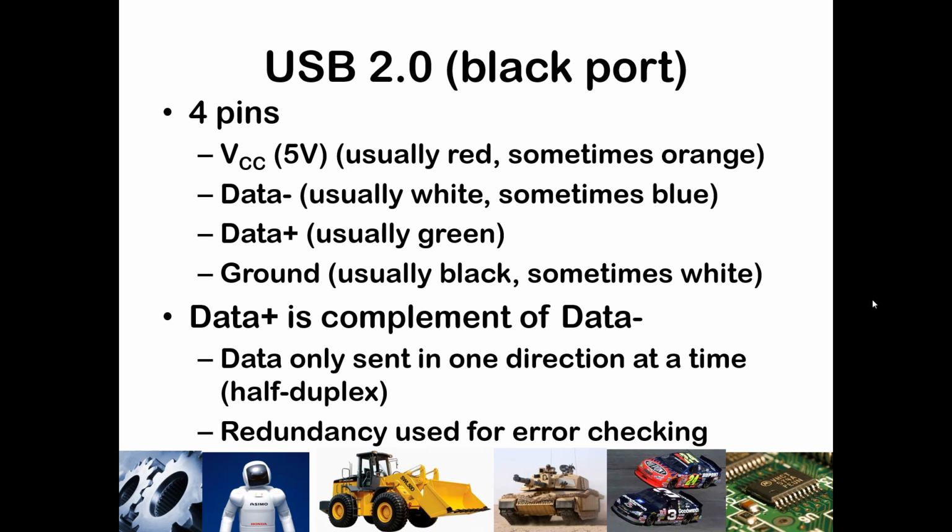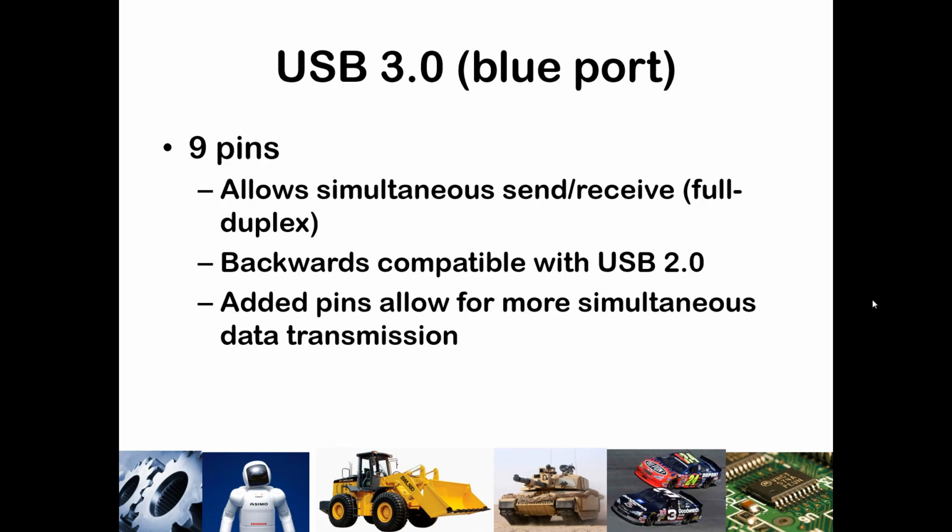a USB. USB 3.0 actually added more pins, and that allows for simultaneous or full duplex simultaneous send and receive. And it is backwards compatible with USB 2.0 devices, so if you have devices designed for USB 2.0, you've probably found that they can still fit in a USB 3.0 port. You can tell you have a USB 3.0 port because it has a blue color inside of the port on the computer. And those added pins allow us to have more simultaneous data transmission.